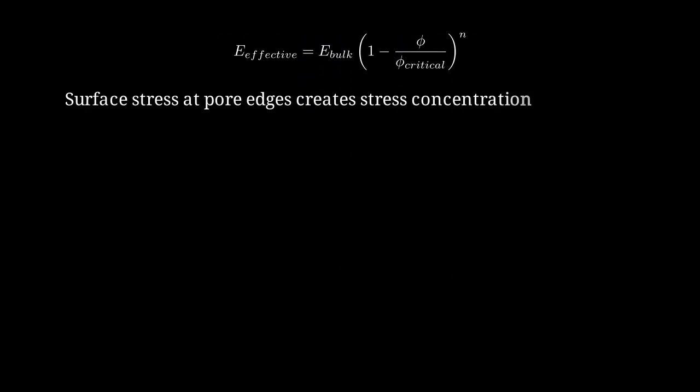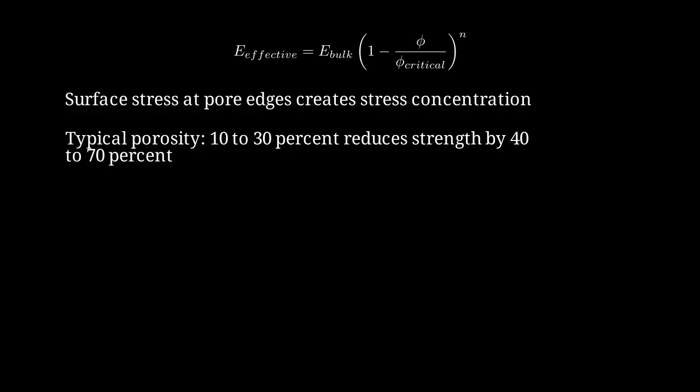Surface stress at pore edges creates stress concentrations that can initiate failure at lower loads. A typical porosity of 10 to 30% can reduce shell strength by 40 to 70%.